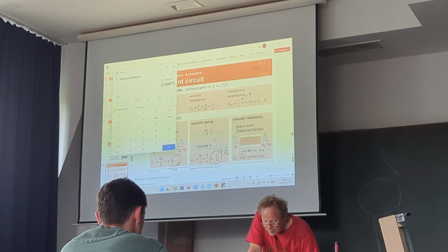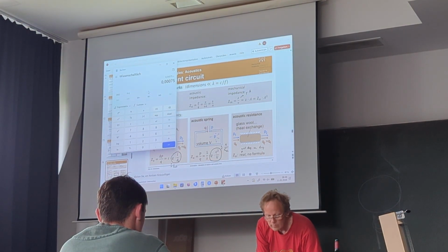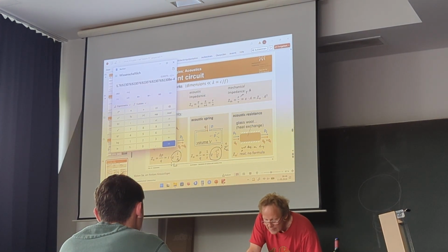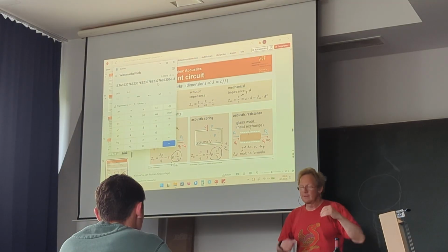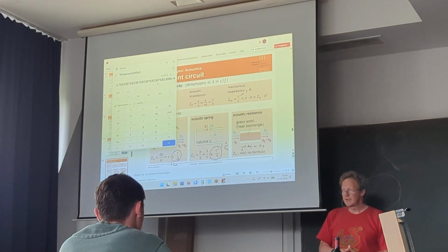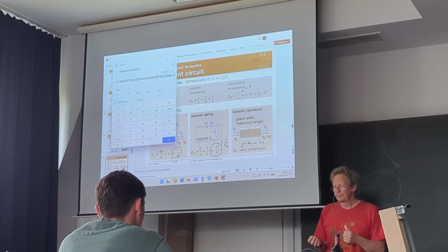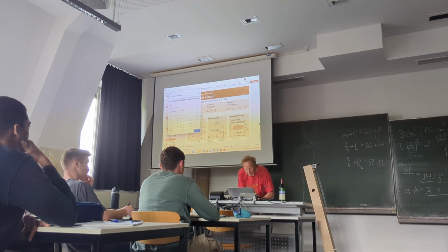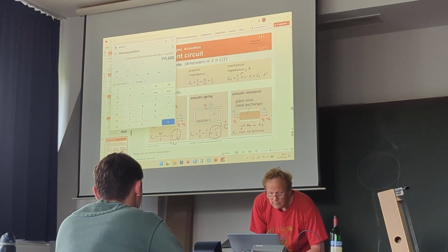Okay, then divided by rho, 1.3. And the speed of sound. It depends a little bit on the height, but in the slides we said around 340 meters per second. So then let's divide it by 340 squared.